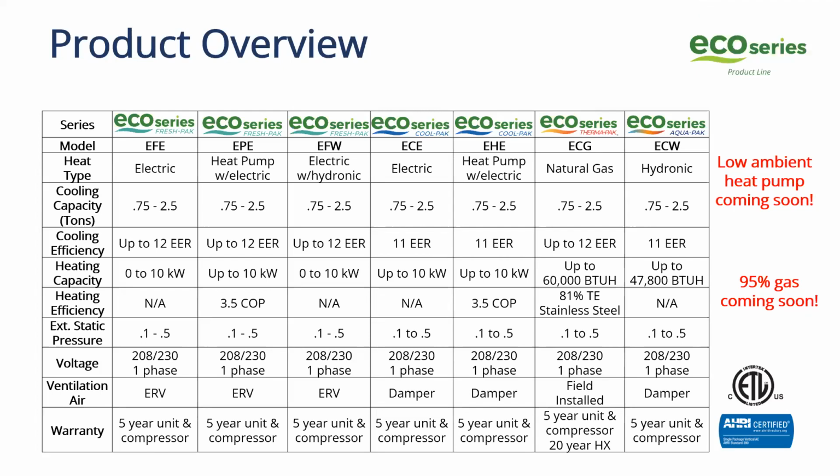Got it. Okay, so it would require them to cut holes in the side of the building to accommodate it, and depending on if there's duct work or not already in that situation, you'd also have to add some sort of minimal duct work, at least on the supply side, to get the airflow to the multiple rooms. But it's not an exact replacement, though it can be done.